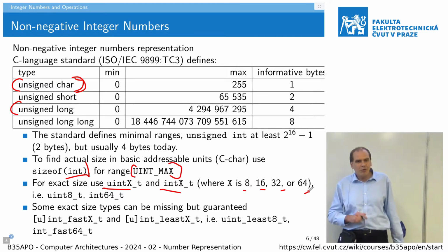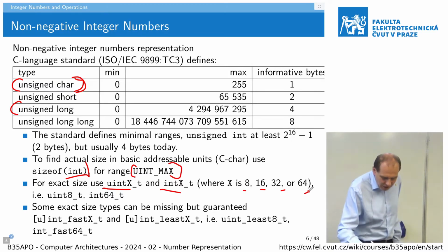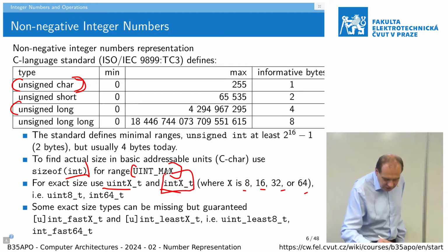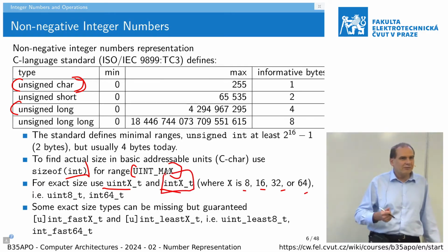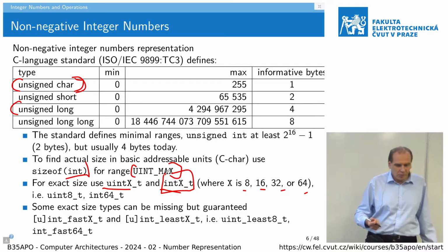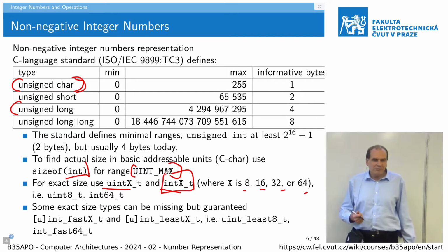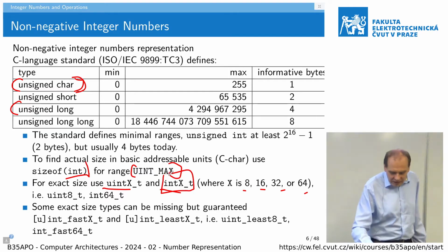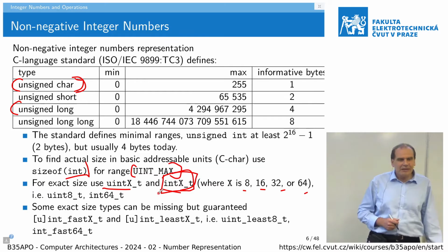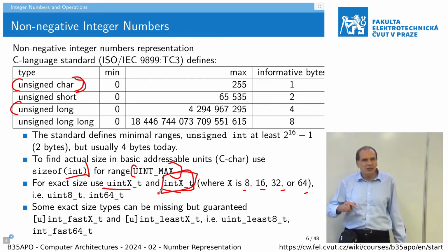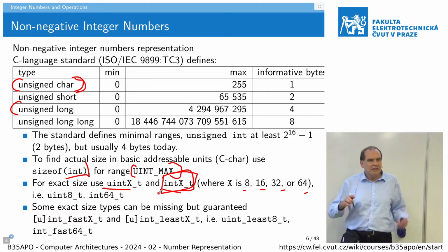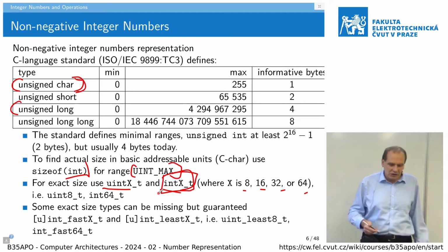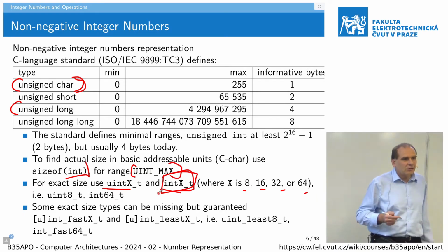It has a problem that if you try to define a type which requires 8 bits on a system which doesn't have an addressable unit of 8 bits, then you cannot compile the code. And sometimes, for example, on an ARM, if you define char or 8-bit integer, then some operations are slower because they have to be masked to 8 bits, when you use a standard operation for 32-bit values.